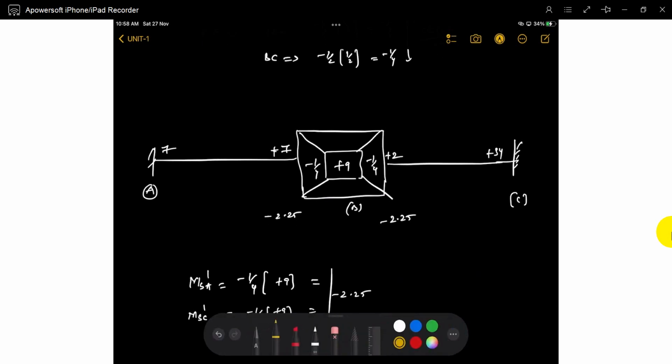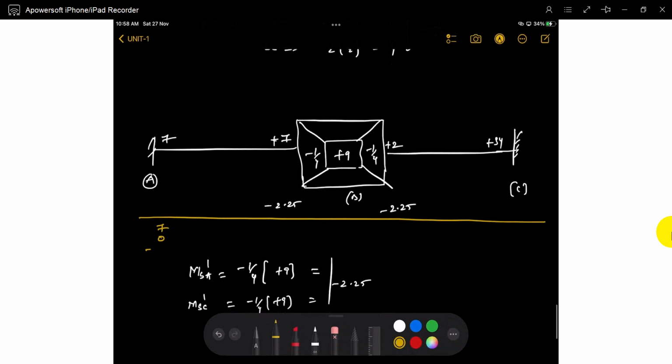That's enough. Very easy. Now you can see 7. Its own contribution is 0. So the previous contribution is from the far end. 7 minus 2.25, so 4.75. Here you can directly multiply with 2. 2.25 multiplied with 2, answer minus 7, it's minus 2.5, so it's a plus 2.5.